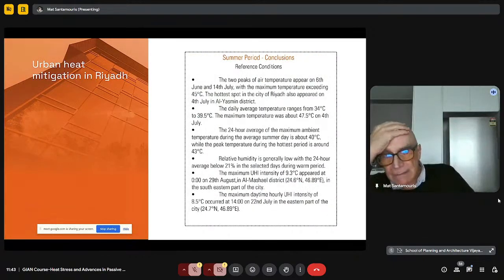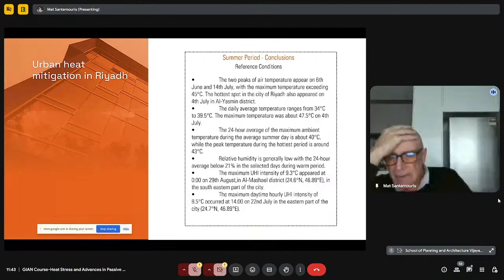How can we decrease the sensible heat? By decreasing the surface temperature. How to decrease the surface temperature? By using materials which do not absorb heat, so they have much lower temperature, and by using greenery, which really presents much lower surface temperature, if it can be used.